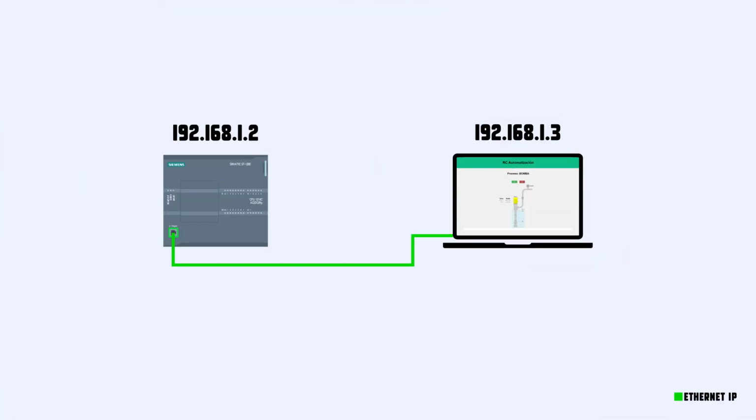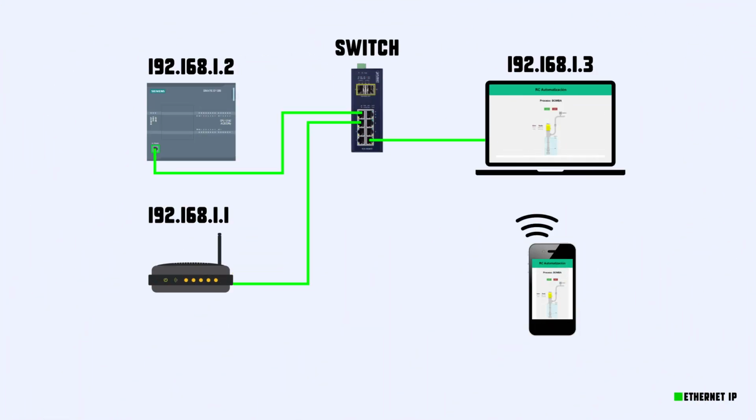I want to clarify that in a real case we will simply have to connect the PLC, previously configured and programmed with TIA Portal, which in this case will be the web server, to a PC or a laptop, where we will view or modify the PLC variables through an HMI using any web browser. We could also use a router to access the user page and modify or view the PLC variables wirelessly through another device.